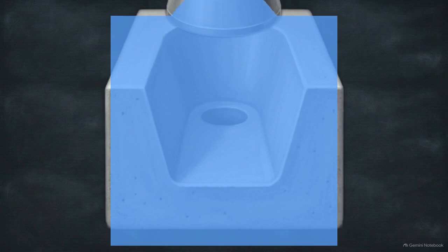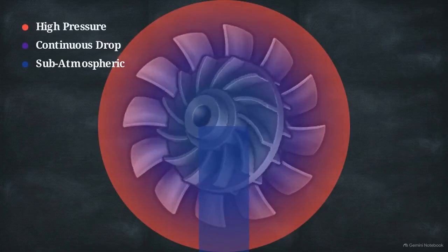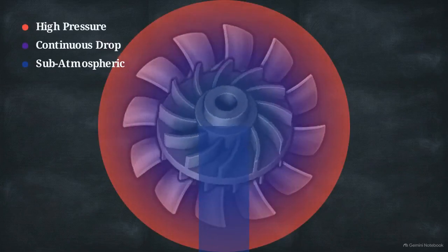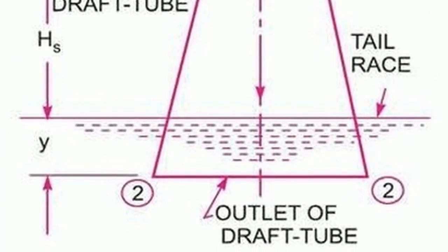A sealed, airtight water column maintains a continuous pull on the runner, actively manipulating fluid pressure to extract additional mechanical work. As water forces through the turbine's guide vanes and spins the runner, its pressure drops continuously. This diagram maps flow down the diverging draft tube. Its cross-sectional area steadily increases. Low-pressure water at the runner outlet must overcome the higher-pressure tail race below. By widening, the tube drops fluid velocity, increasing pressure above atmospheric before exiting.